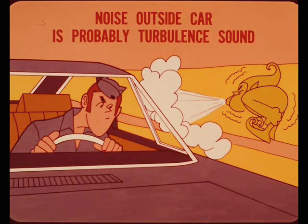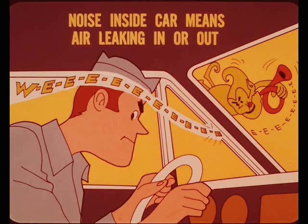If the noise seems to be somewhere outside the car, it's probably a turbulent sound. Locating the source may take some experimenting because the sound and its cause may be in different locations. It's basically a cut-and-try process. When the noise sounds off inside the car, it usually means that air is leaking into or out of the car body.